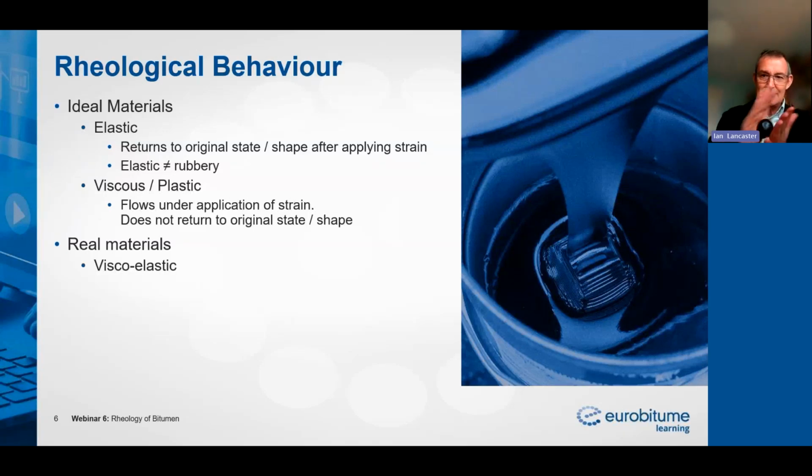So this little sample here, which is silly putty, but it mimics the behavior of bitumen, it bounces back. But look at what happens if we apply a really low frequency stress to it. It deforms, but then when we take the load off, it stays deformed. That's why bitumen is such an interesting material.